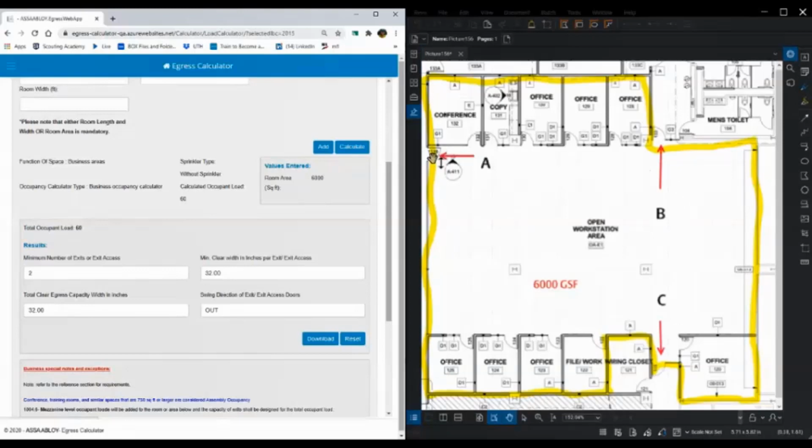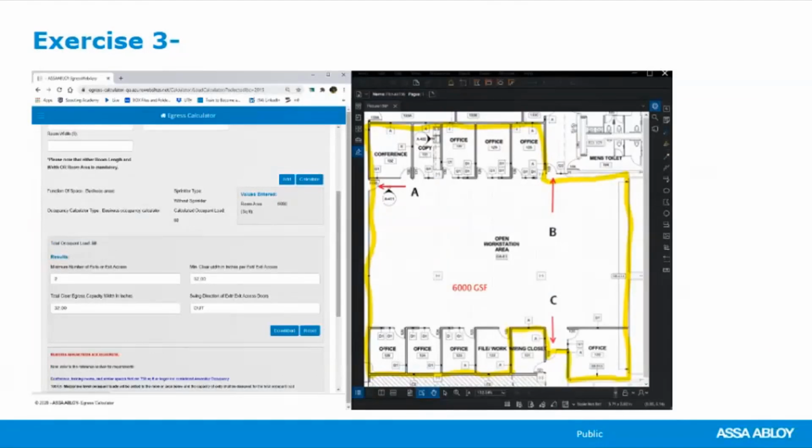There wouldn't be a lighted exit sign above here, but these 2 doors meet your requirements for means of egress, and you don't need exit devices on any of those 3 doors. And just because the code does not require exit devices doesn't mean that you can't use them. They may be the best solution for hardware depending on the type of traffic and how often they're used.